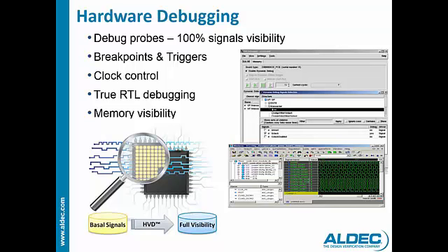These are the signals essential for debugging, and they have to be captured from the hardware in order to provide full visibility. Then a hardware debug algorithm can be used to expand these basal signals to give full visibility. Basically, flip-flop and memory signals are captured, and then the combinatorial signals can be computed.